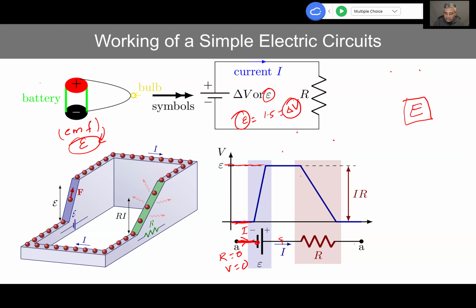And then what happens once the electron, let's say, reaches the point where there is now resistance, it starts losing energy, okay? And once it gets out, what happens? It arrives to this same point as A. So whatever voltage we have over here, this is going to have same voltage. So if we assume negative as 0 and this has 9-volt, how is it going to look like? Over here, 0, over here, 9-volt, all the way up to here, it is 9-volt, okay?